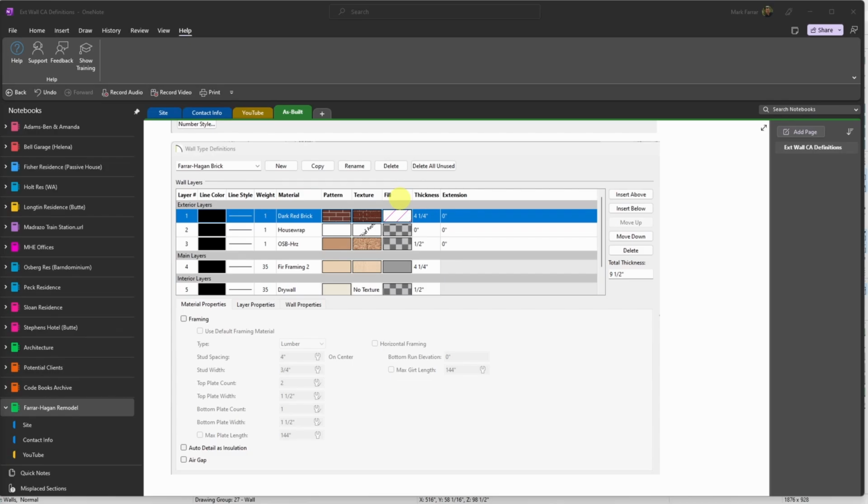Offset in for a stem wall, that's 8 inches. This line is on a different layer than my interior line for that reason, so that I can manipulate it and turn this layer off on the foundation plan and use this line as is. So Xrefing in the floor plan, if any changes occur, they just pick up right away into the foundation plan. So, some shortcut items.